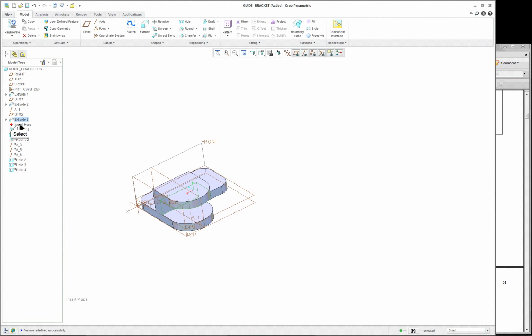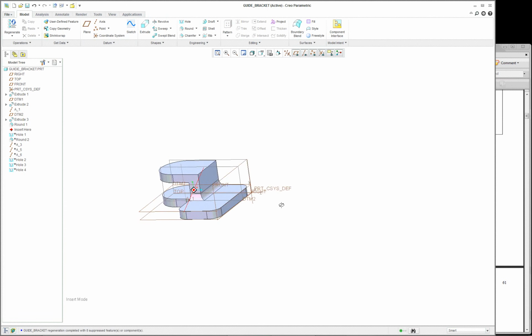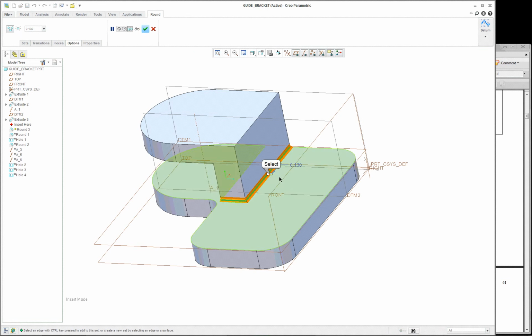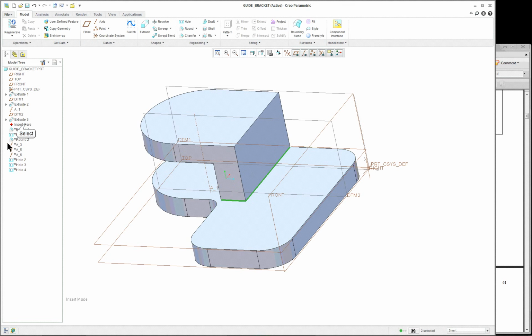Back over here, let's take and round. Now, the round command here is very simple. You're just using the 2 edges here. So click on the model, click on a feature, I should say, right mouse button, move your cursor, click on it, hold down the control key, select again. So now both of those edges are selected. Right mouse button, round edges. And then drag it to the size you want, or type it in. Get rid of that one. We'll keep the one I already have modeled.